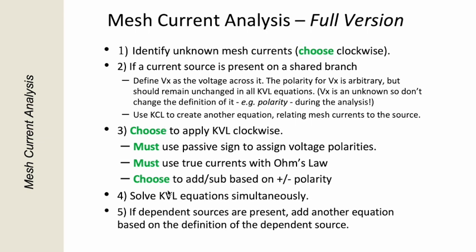Step 3 involves KVL. Easy now with that current source because we have voltage across it, so we can readily incorporate its voltage into the KVL equations, solve, and then of course an additional step, it's worth mentioning, if dependent sources are present, then we need to add another equation based on the definition of that dependent source.